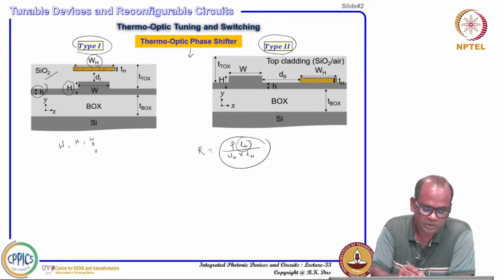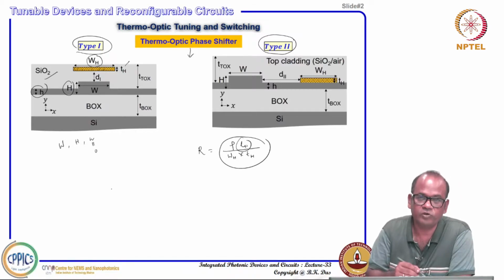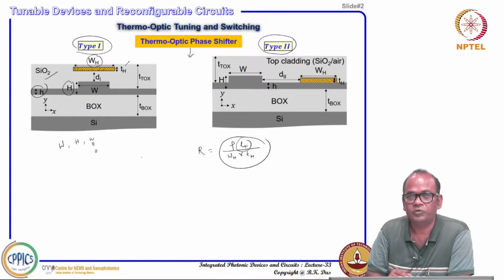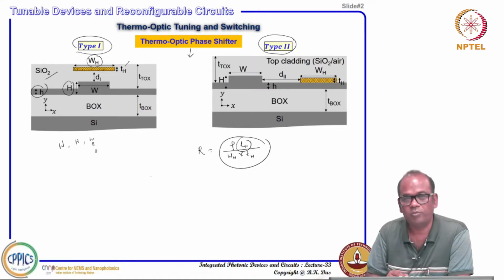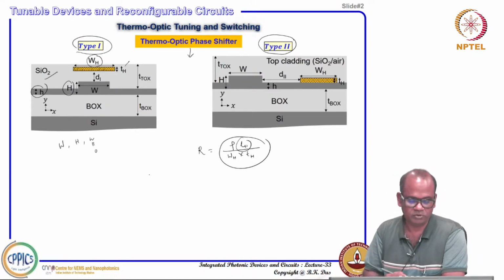On top of it, you can again have a silicon dioxide layer, deposited to passivate everything, and where you want to make a contact, you can open the oxide and do wire bonding, or make some contact out of the device.